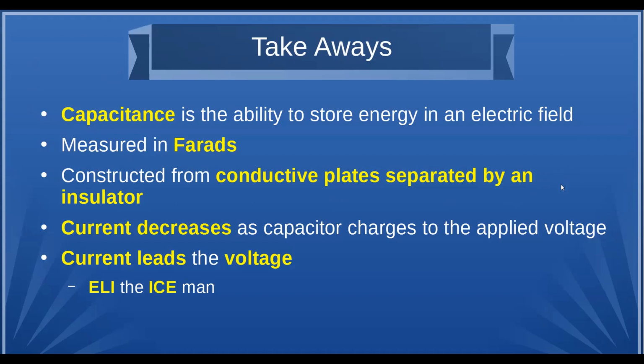Another test question. Current decreases as the capacitor charges up to the applied voltage. And we talk about the current leads the voltage. Okay. The current goes up instantly. The voltage goes up slowly. Okay. And there's a little memorization thing called ELI the ICEman, where